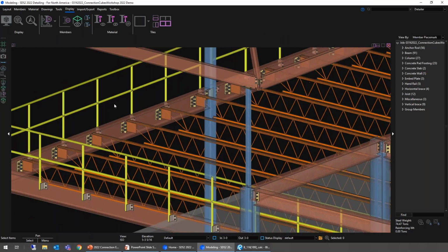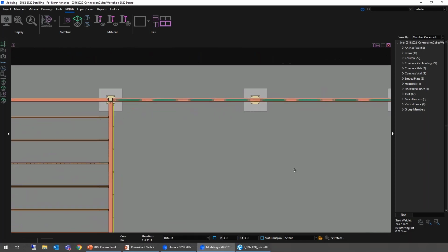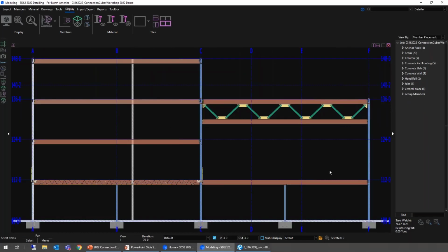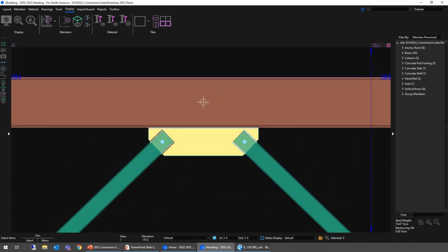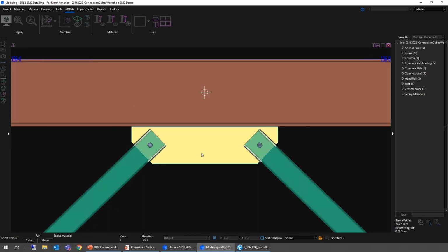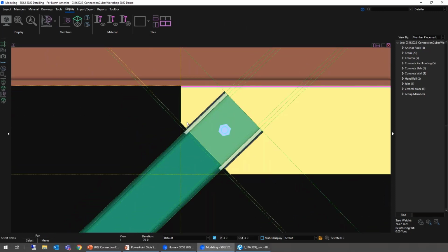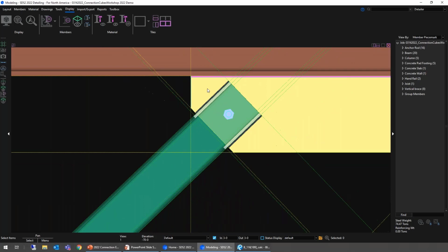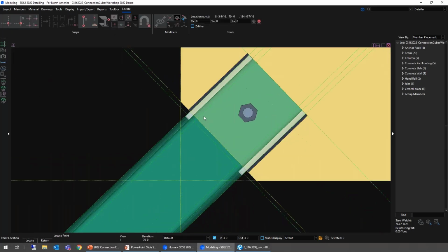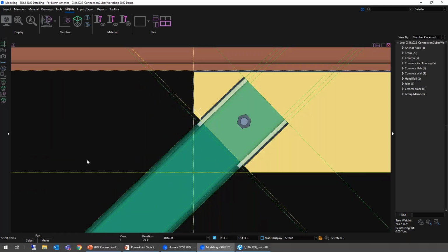Last topic we have to cover here then is that gusset shoulder dimension. This is my favorite, just because I know what users had to go through in the past in order to adjust this. So just to show you what we have right now, remember from my slide, the shoulder dimension is the distance from the face of my tube in this case to the corner of my gusset. And if I were to add a dimension on there for us, okay, we've got 1 inch right now.